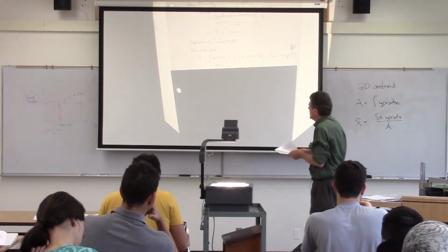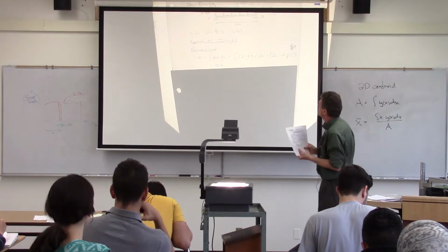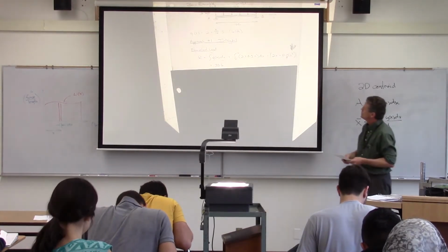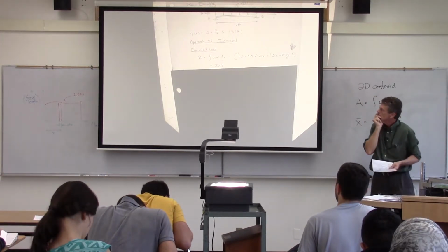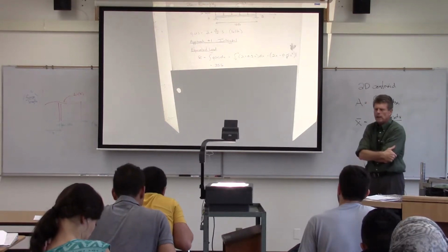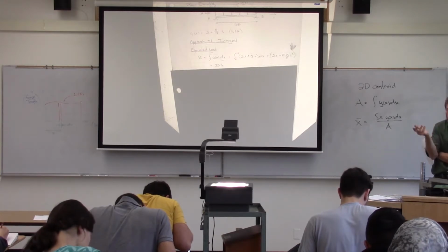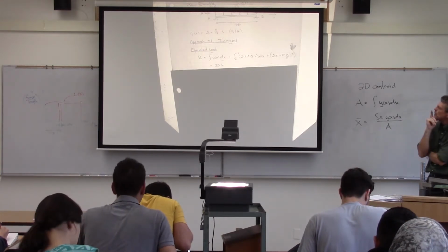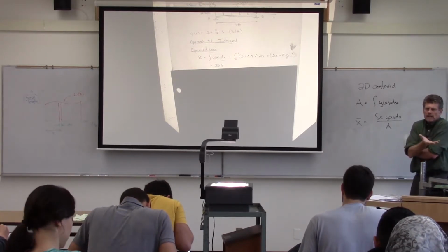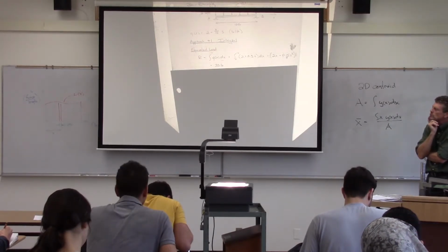It's simply, again, integrating the area under the load curve. So I'm going to take that q(x), which I've now expressed in terms of that linear function, plug it in, do the integration, and take it between the limits of 0 and 10. What I end up with is the equivalent magnitude of that distributed load that starts off at 2 and ends up at 5 pounds per foot, which will be 35 pounds. So if I were to take that beam and weigh it, the distributed load would come to 35 pounds.